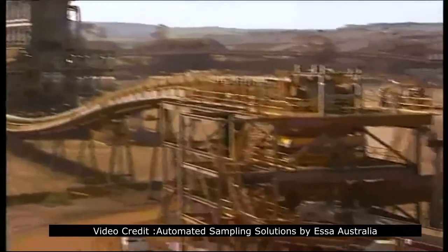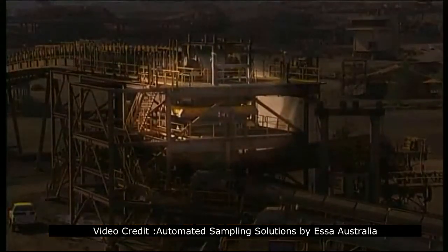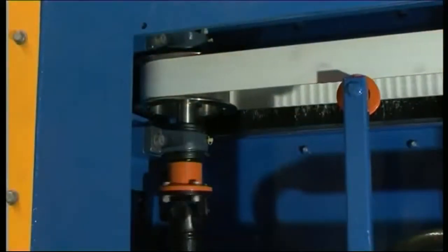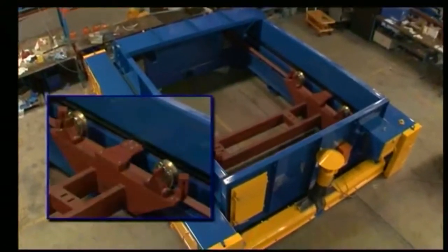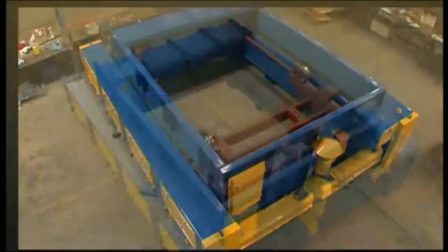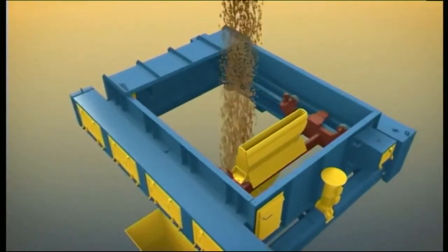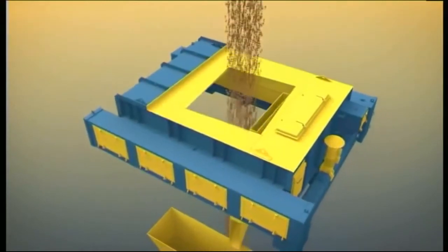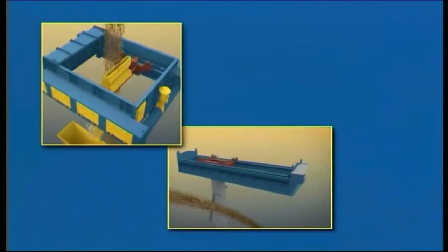Where the sampler has to be mounted below the discharge point, a synchronous belt drive sampler is used. A single electric motor drives two synchronised toothed belts located either side of the ore stream. This allows the sampler drive and cutter to operate on the same plane across the falling ore stream. This design is suited to high tonnage shipment conveyors. These belt drive samplers adhere to the same good sampling practices.